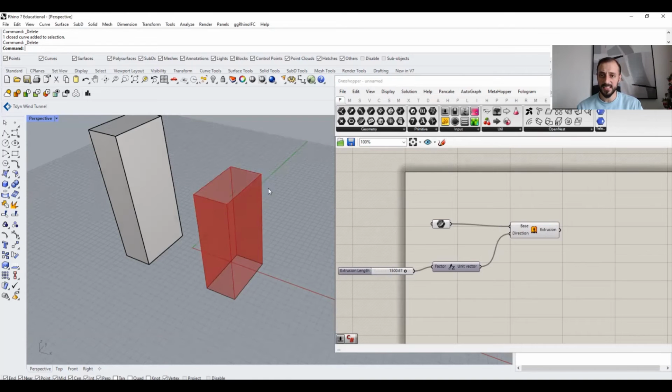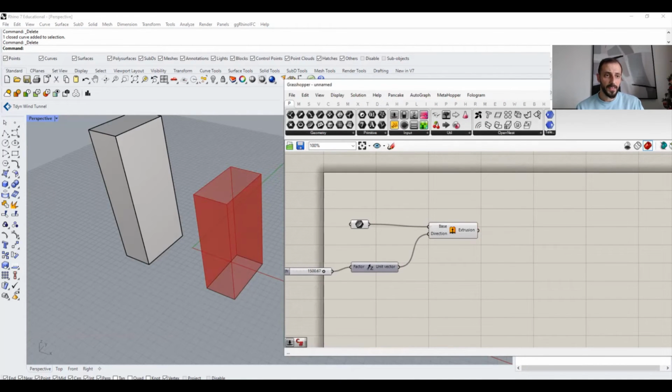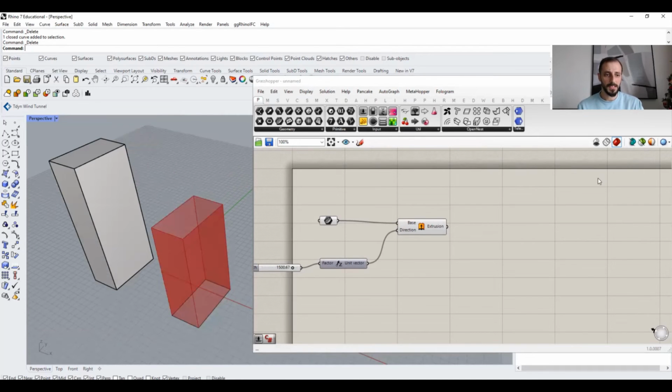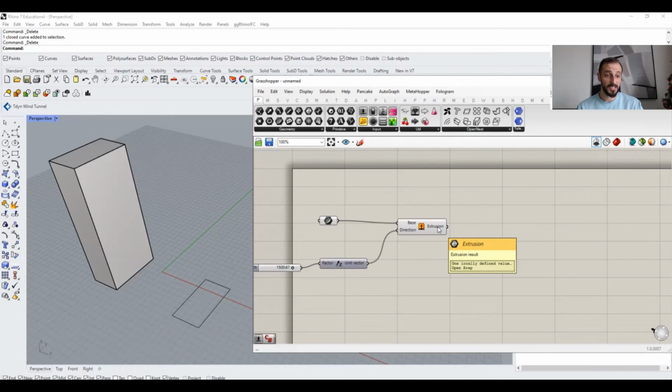So you cannot select any of these geometries, right? Speaking of previews, if you come over to this spot, what we are seeing is related to how we see things in Grasshopper. If I click on this button, which has a closed eye in front of a cylinder, I assume, it says don't draw any preview geometry. So if I select this, even though it has a geometry inside as a result of our extrusion operation, we don't see anything.